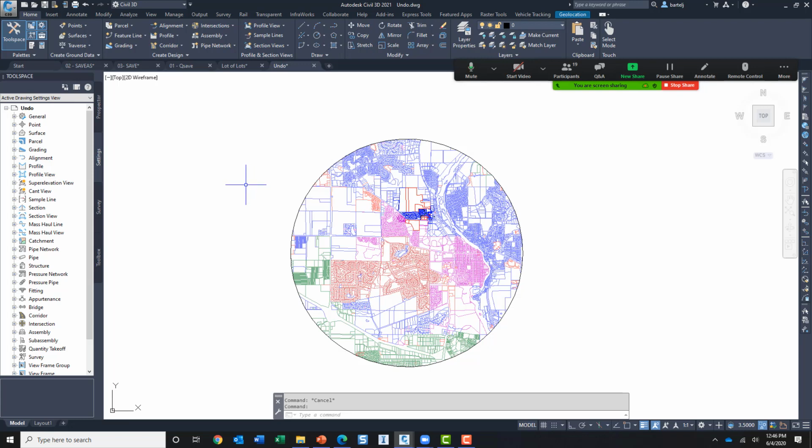It's one of those things, it's like ketchup. More isn't necessarily better. You want to make sure and set it only in the files that you're X-referencing, because when it's creating the indexes, it will actually increase the size of the file. And if I had to throw out a rough number, it would maybe increase the size of the file 5 to 10% for the extra information that's required. All right, so no reason to make your files bigger than they need to be.